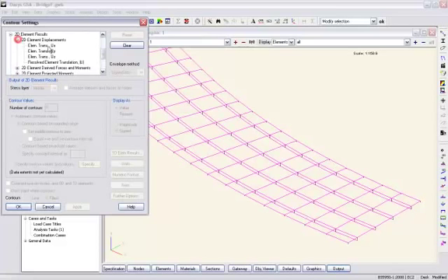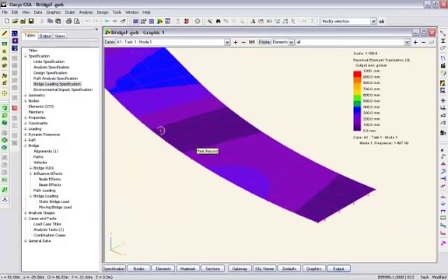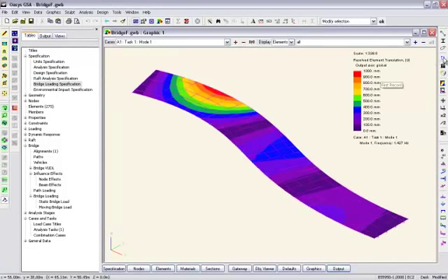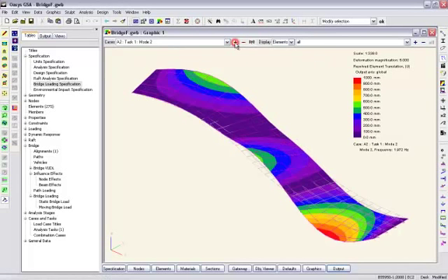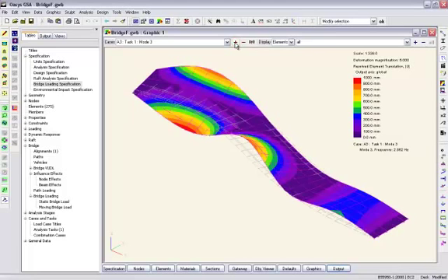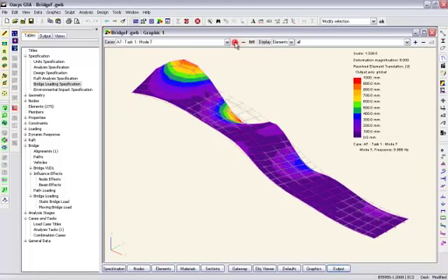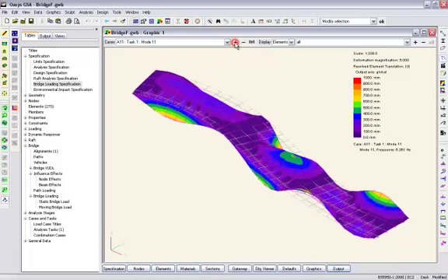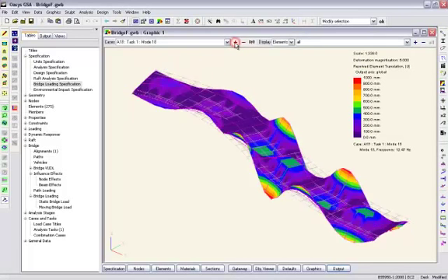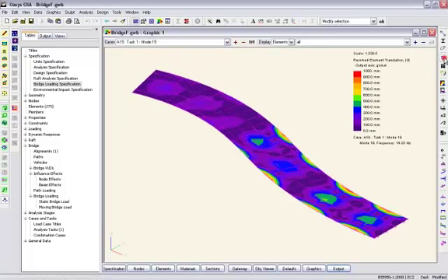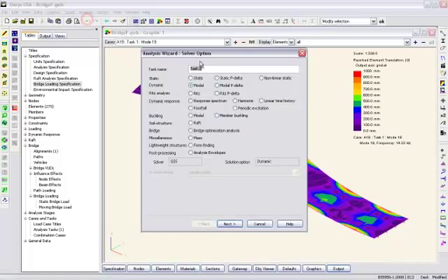So, displacement contours and displacement shapes. You see there is the first mode, second mode. I'll just quickly run through these, make sure they all look sensible, nothing untoward. Wonderful. They look good. Okay, once we're happy with those vibration modes, we then need to do a second analysis, which is the footfall